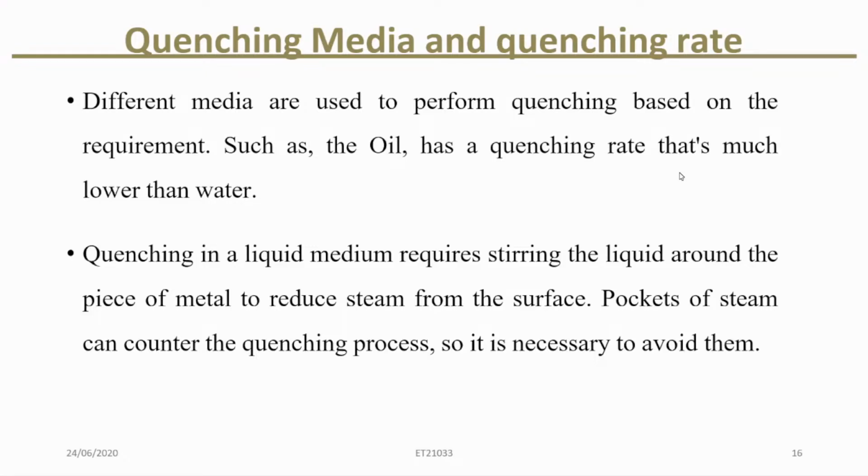When quenching in any liquid, don't just drop the part in and walk away. You must move the liquid around the part, okay? Because a hot surface makes a steam blanket that insulates the metal and slows or unevenly cools it. Good agitation sweeps away the steam, keeps fresh liquid touching the surface, and gives a more uniform, reliable quench.